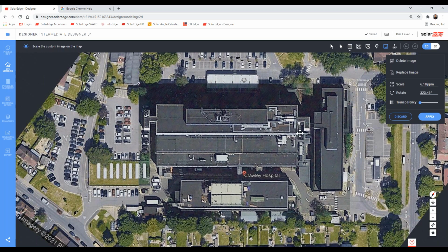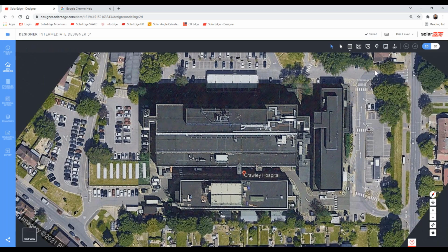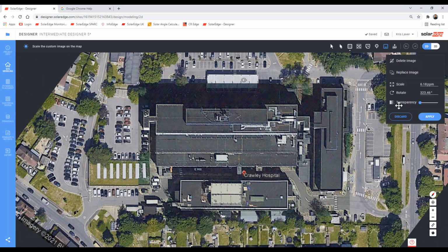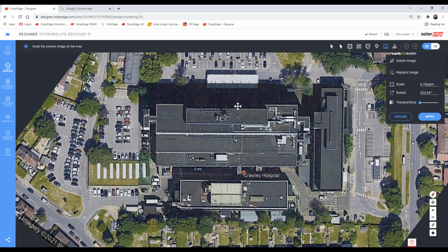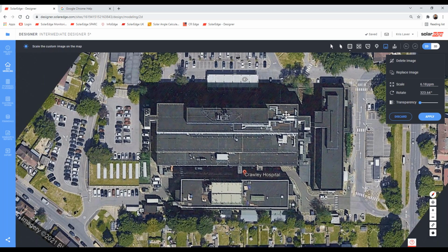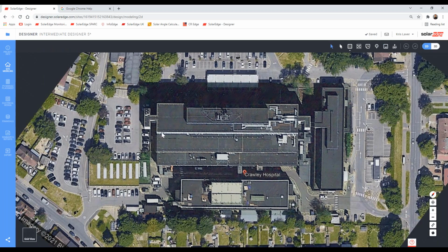No worries. And you can spend as much time as you like, really. Sometimes the lollipops, you won't have got them quite right the first time. If that happens, you can discard the image, re-edit. You can resize it here. I'd err on the side of caution with that. You can rotate it here. You can rotate it here also. But once you deviate too far away from the original, you can lose yourself quite easily. So if in doubt, just discard the image and start again. And now anything you model will be to that new image. It's a great feature. I use it pretty much every day.